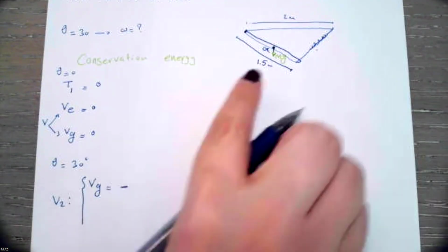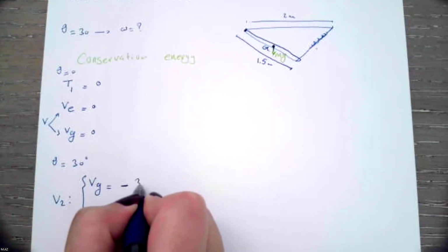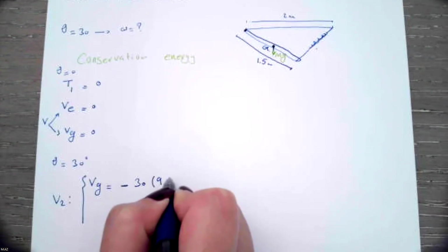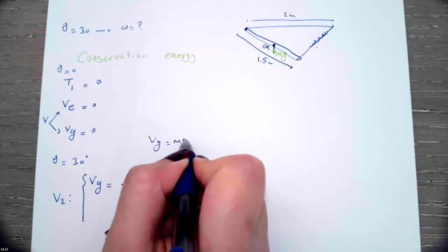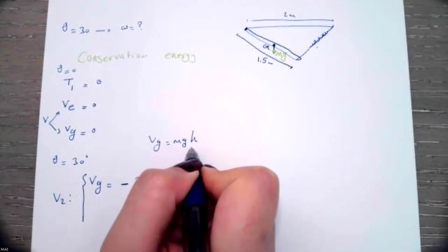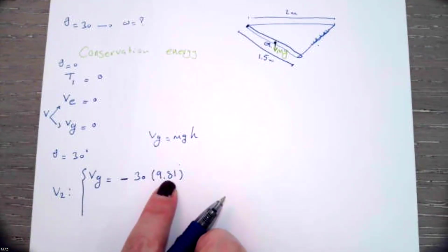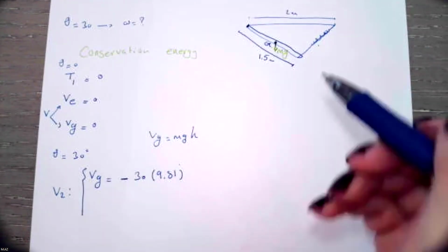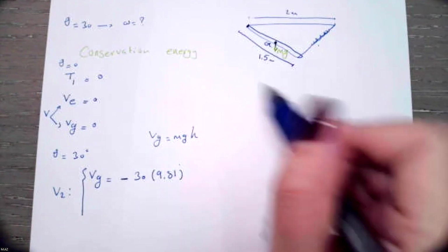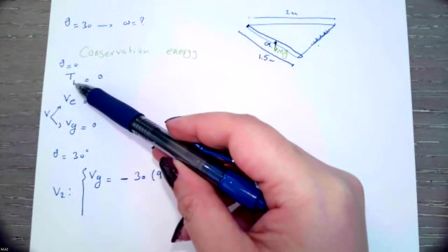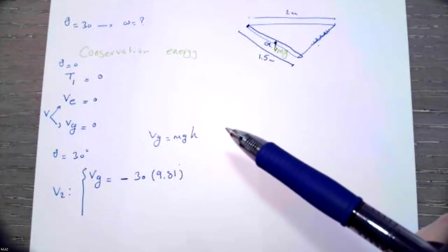The mass of the rod is 30 kilograms. The gravitational potential energy is mg times h. This is below a datum, so we have negative 30 g. And how about the height? We are working with a rigid body, okay? And if you remember, I mentioned we are applying the kinetic energy and potential energy at the center of the mass of the object, okay?